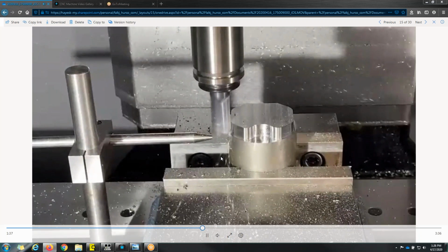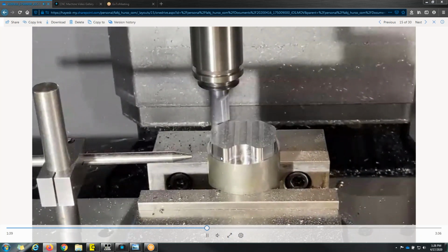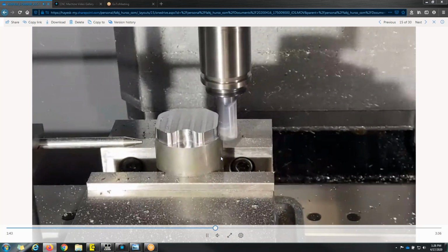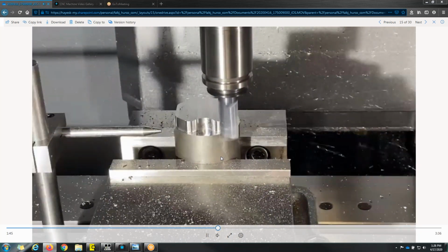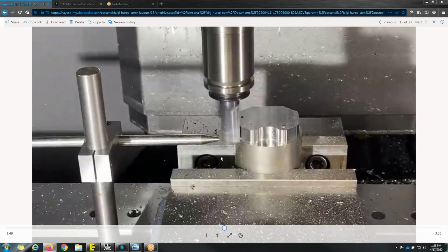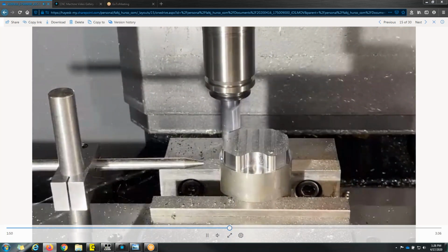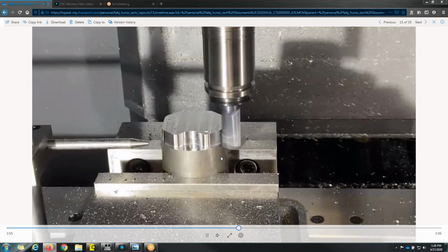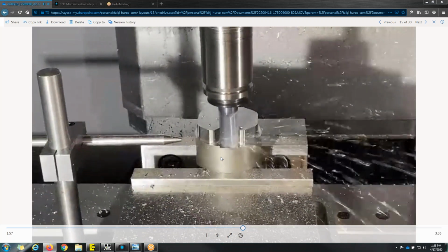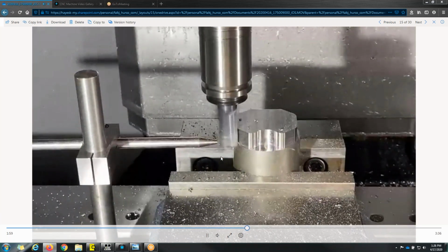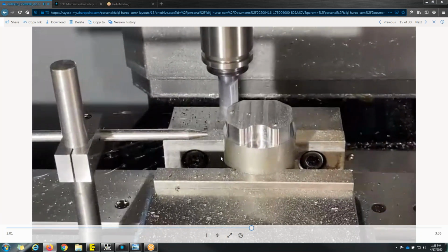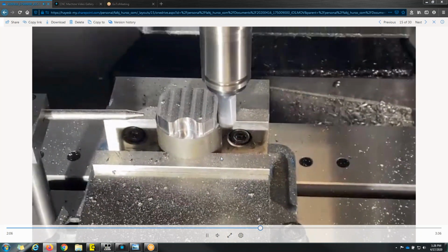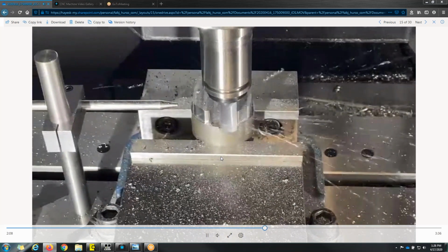Also, if you're doing extremely deep contours, maybe you have an inserted cutter and you're going around the outside and you don't have a whole lot of flute length on your cutter, this is a nice way to get a smooth, consistent surface finish all the way down that wall. You'll notice that there is no blend in and out. It is a constant ramping motion on that wall, so you should get a very nice surface finish with no transition witness marks when it's all said and done.